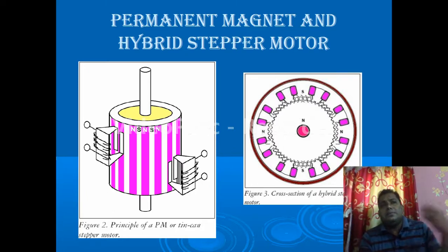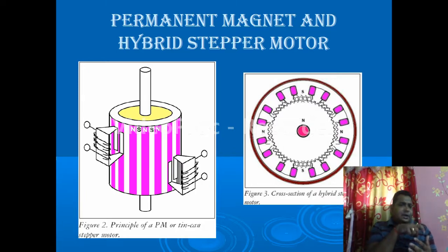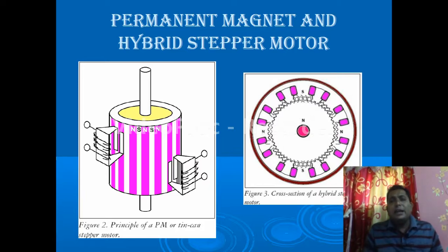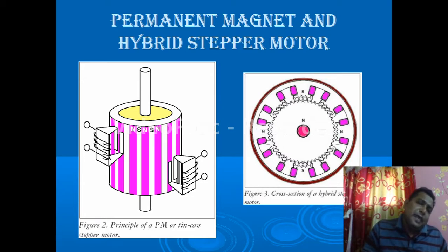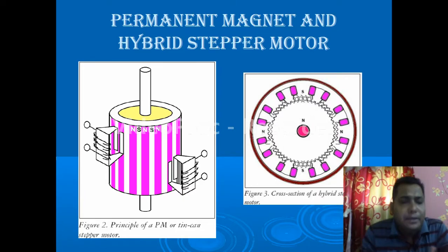That means the stator poles are acting as magnetic poles. Now we will give the supply. The stator generates alternate north south poles, and in the rotor section we also have north south. We know that the same poles repel each other, and the opposite poles attract each other. Depending upon this principle, this machine works.